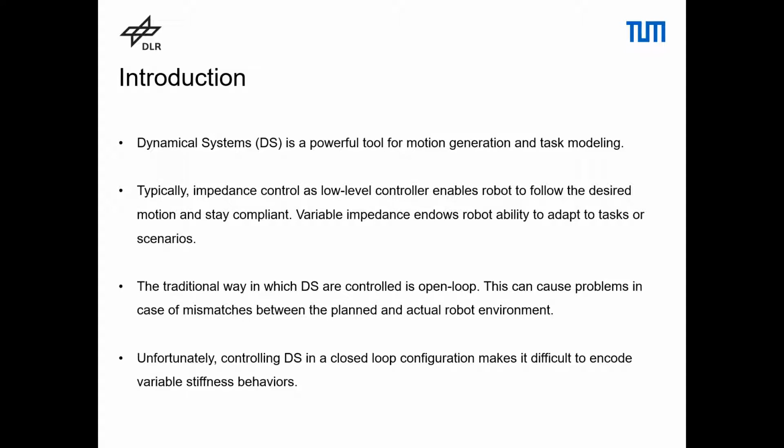In such a configuration, the motion generation loop does not have any feedback about the robot state and therefore cannot react to perturbation directly. Thus, the accumulated error from motion mismatch can cause large interaction force to the environment.